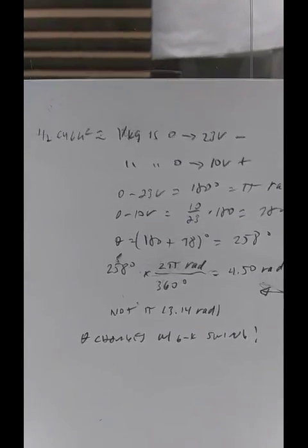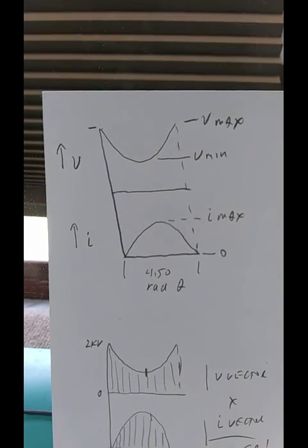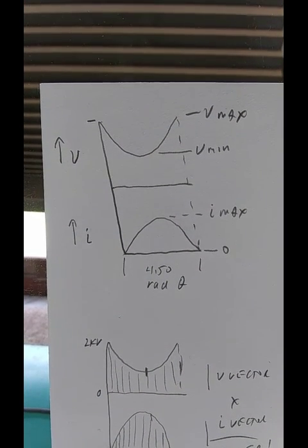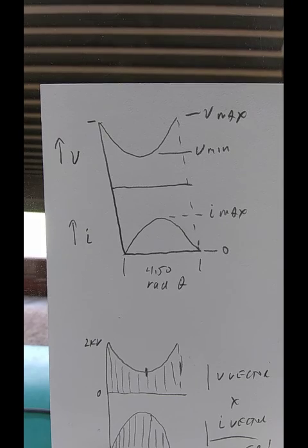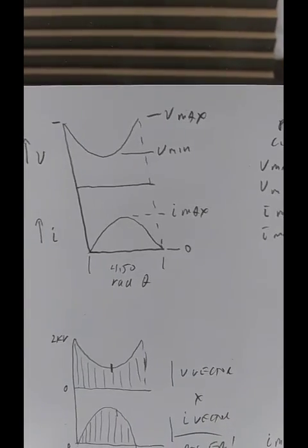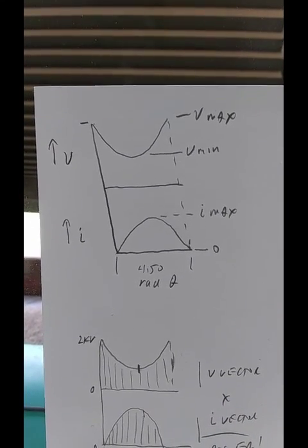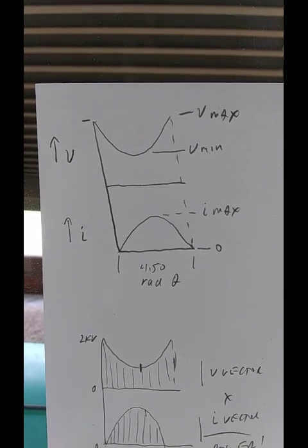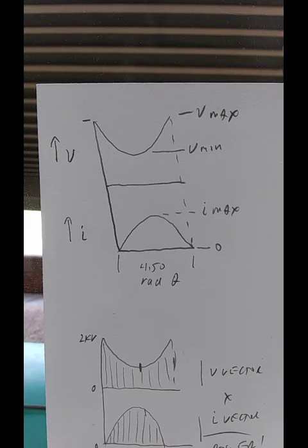There's a complication here. If you happen to notice at the bottom of that graph, 4.5 radians, not pi, not 3.14. In the case for a lower plate voltage and current, that's only a 23 volt grid swing in negative, or cathode swing in a negative direction.